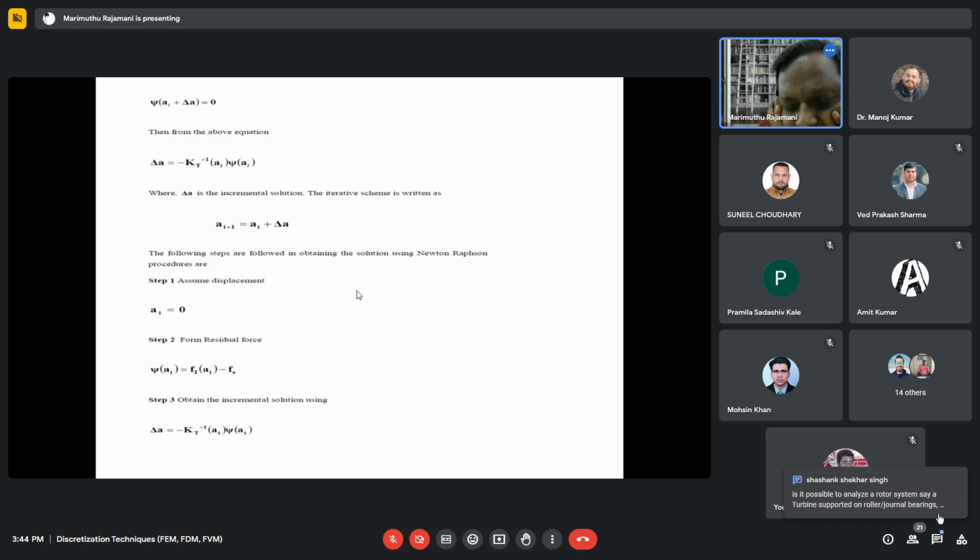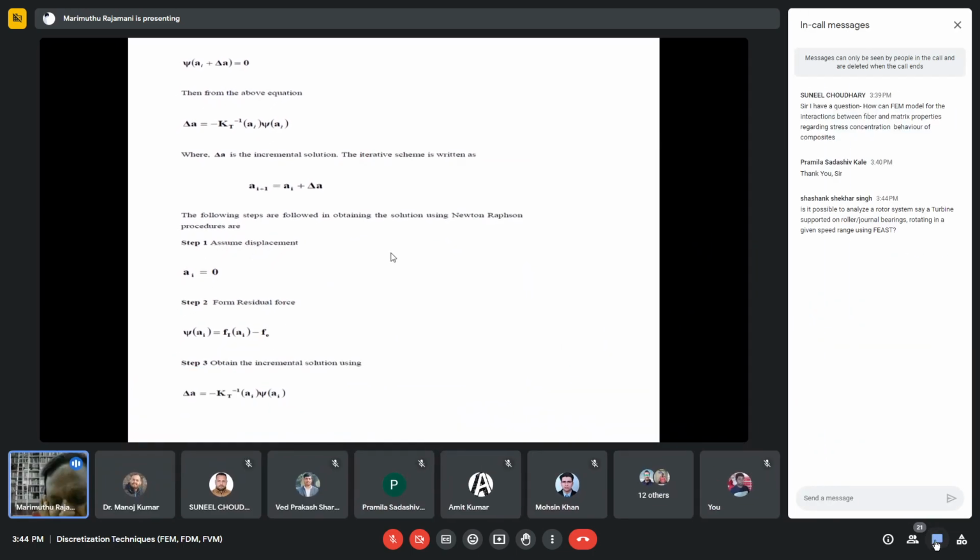Afterwards, whatever results you get through finite element are accepted as the solution, and it is your duty to make the right kind of boundary condition, right loading, and make sure of everything, and then you have to accept the results. Further, if you want to confirm, then experimental validation is the only thing left.